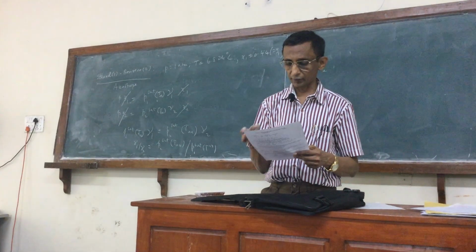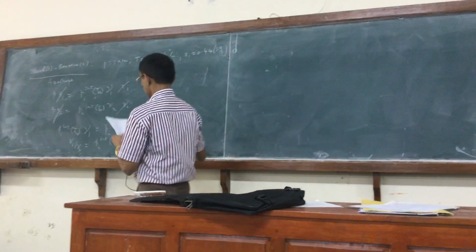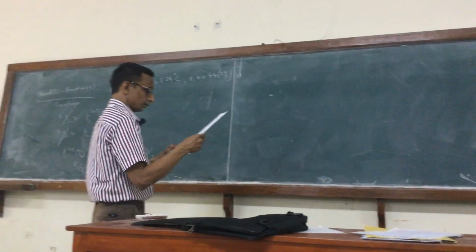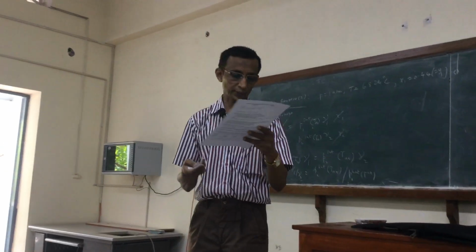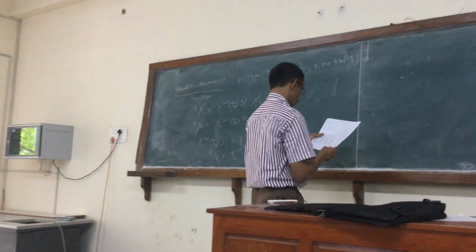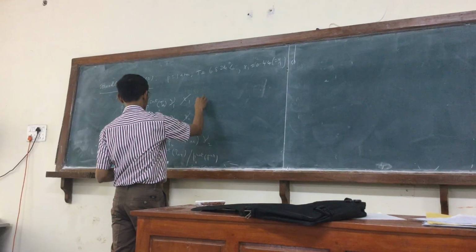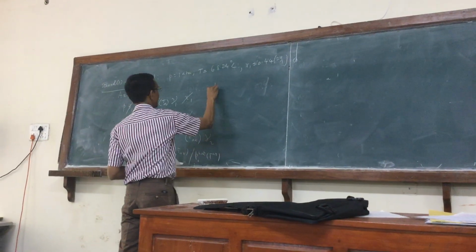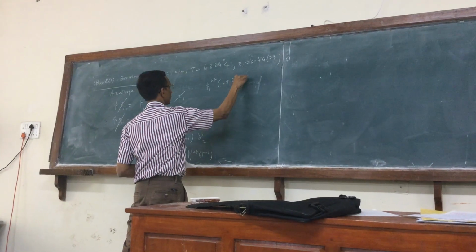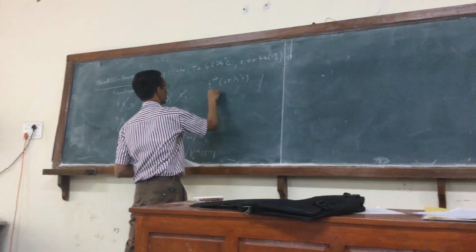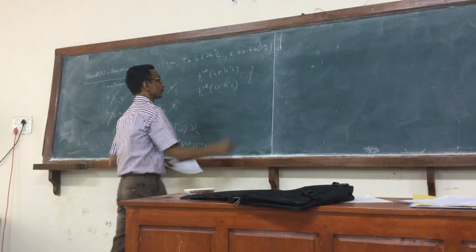So what do we do with this? Now we have to choose a particular component. So let's calculate for ethanol. You are also given the Antoine parameters for ethanol and benzene. So ethanol is supposed to be component number 1. And so what I have to do is calculate P1sat at 68.24 and P2sat at 68.24 degrees centigrade.